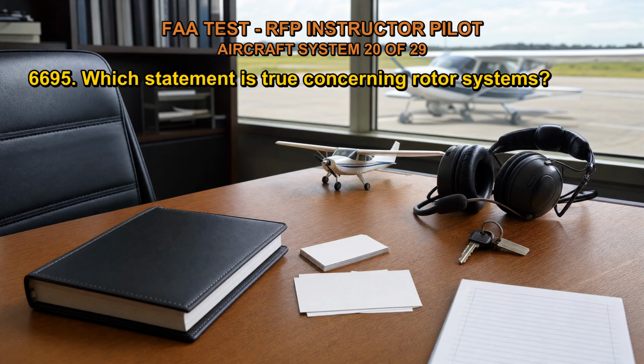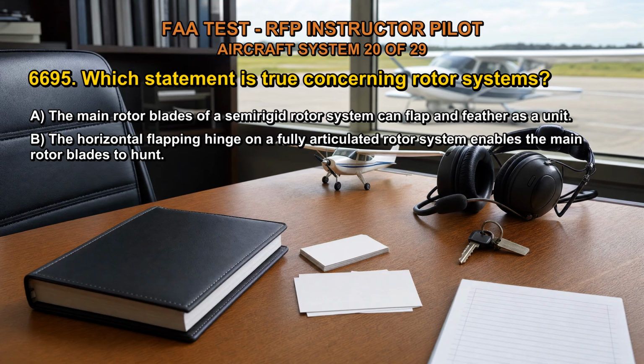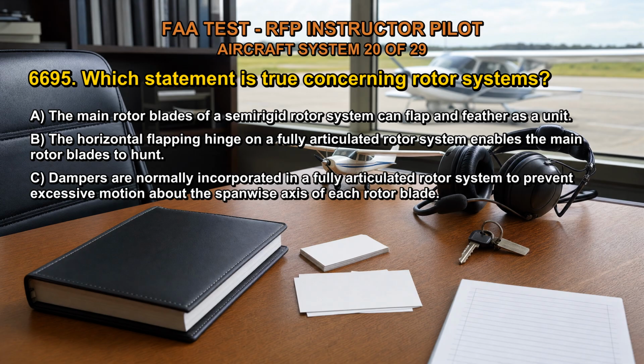6695. Which statement is true concerning rotor systems? A. The main rotor blades of a semi-rigid rotor system can flap and feather as a unit. B. The horizontal flapping hinge on a fully articulated rotor system enables the main rotor blades to hunt. C. Dampers are normally incorporated in a fully articulated rotor system to prevent excessive motion about the spanwise axis of each rotor blade.